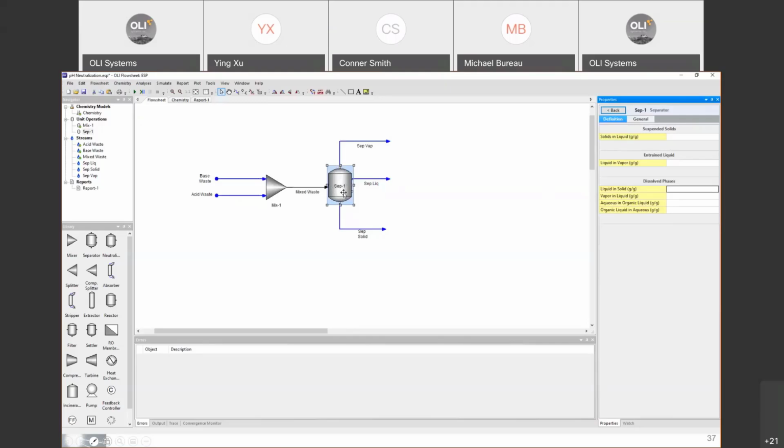However, that means that if you're doing that entrainment, then you will need to use empirical values. You as the user must know these values and enter these values to run the calculation. The option is there. I wanted to highlight that if you don't have 100% separation, you can always simulate how much of that separation is not possible, and then you come here and enter those values.